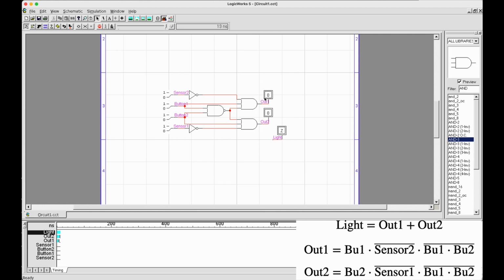Everything looks good, and the output is actually showing up. Finally, let's move this a little bit further. What we also need to do is to design the connection for Z. For this, we're going to use a single AND gate. Let's drag it a little bit further and then connect it to output 1 and output 2.